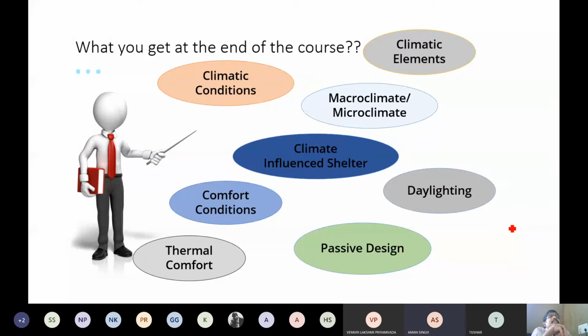Okay, but you can always figure out one thing, that whenever you are looking outside your window in your house or in your hostel, you don't always face the sun, you don't always get the heat inside your room, but generally over the day many a time you get natural light which is soothing to your eyes. Yes or no? Yes, sir. It is not the heat component. You get a reflected component, you get some sky component. So that is where daylight doesn't mean that there is heat going to be involved.